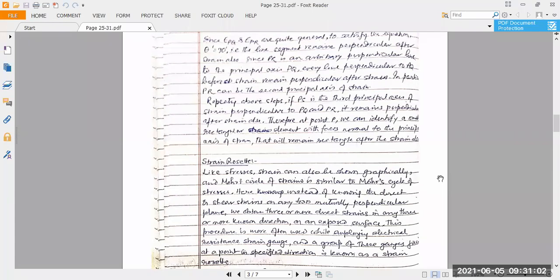We put an angle equal to that theta, which we touch at the intersection at the Mohr circle, and we drop a vertical from that point. From the vertical which reaches the x-axis, we get OX, the normal strain, and the length of the vertical is called the shear strain over a particular plane inclined at an angle theta.